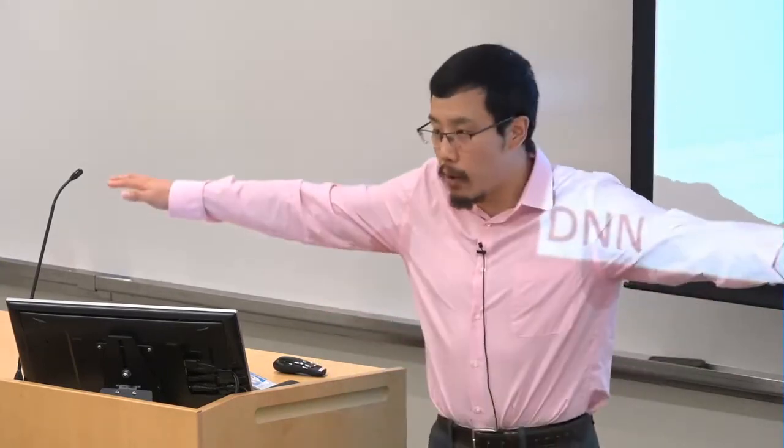Yes, that's a lot. So for the calibration, we perform a T-pose. For this, we assume all the joint angles to be 0, 0, 0. And then we ask the subject to hold the T-pose for like 15 seconds. Because it's stable, we try to recover the relative orientation from the IMU to the body part. We can do that all at the same time. So it's an auto-calibration system. It's automatic. It's not pre-calibration. You don't need to take one and calibrate it. You can do it all by itself at one time.